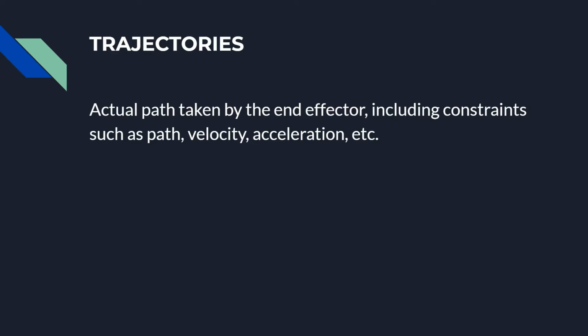And also in our next session, session 4, we will talk about how we have to maintain the total angular velocity and the total torque, because that can actually cause our robot to topple over. If we have a too sudden movement, our robot will fall over. So we have to decide what the velocity, what the acceleration, and all of that is in the course of our path from A to B.